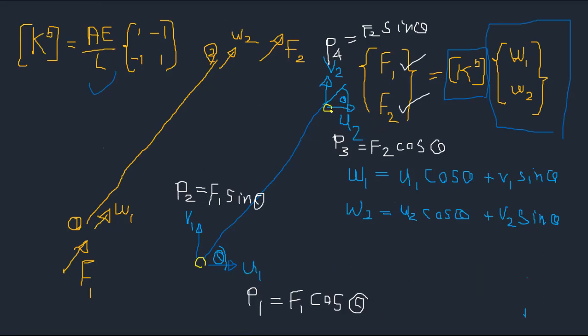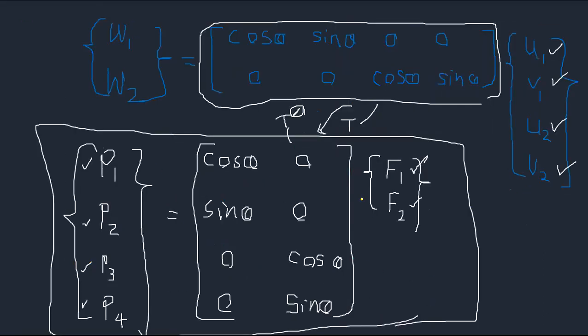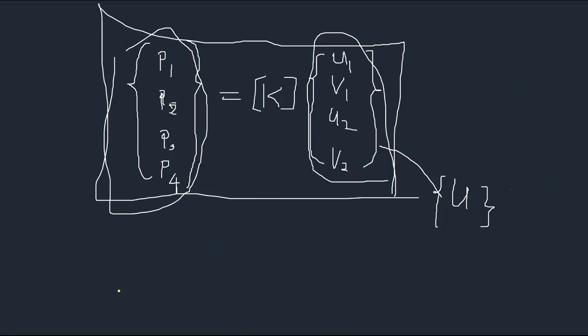So we take the angle as the angle made with the positive x direction. This is 0. This is the first node and this is the second node. If reversed, that is 180. Always define the truss elements like this.